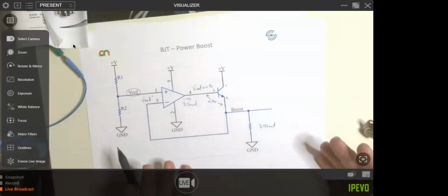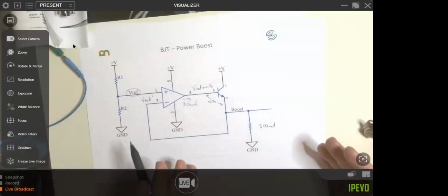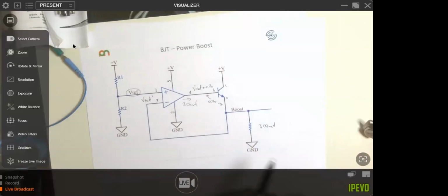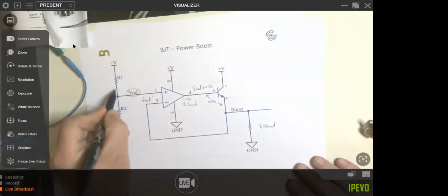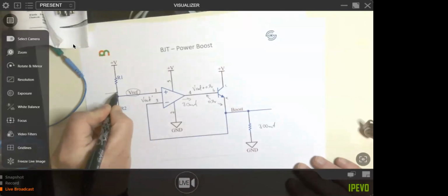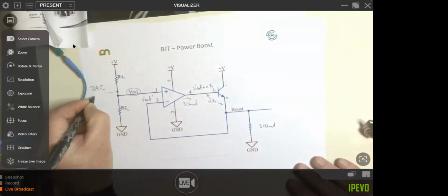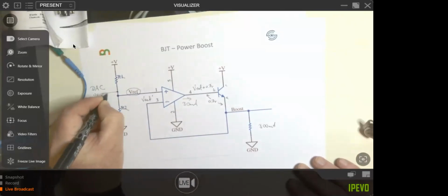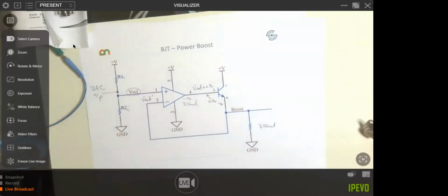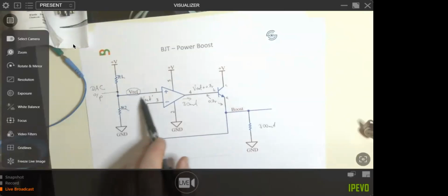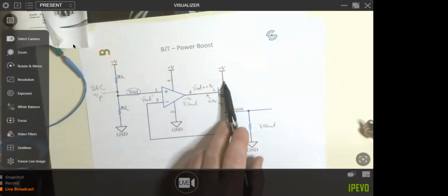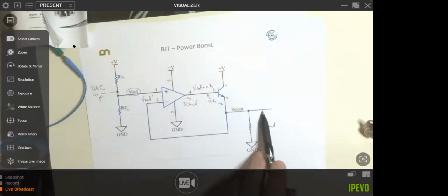And if you want to create a voltage source in your circuit, this is a great and really easy way of doing it. Rather than having this fixed potential divider, if you've got a microcontroller, we could get rid of that and have this as the digital to analog converter output from your microcontroller. In fact, that wouldn't be a bad way of doing it at all. Then this would buffer it, and give you a nice, safe way of getting a nice, clean output voltage.